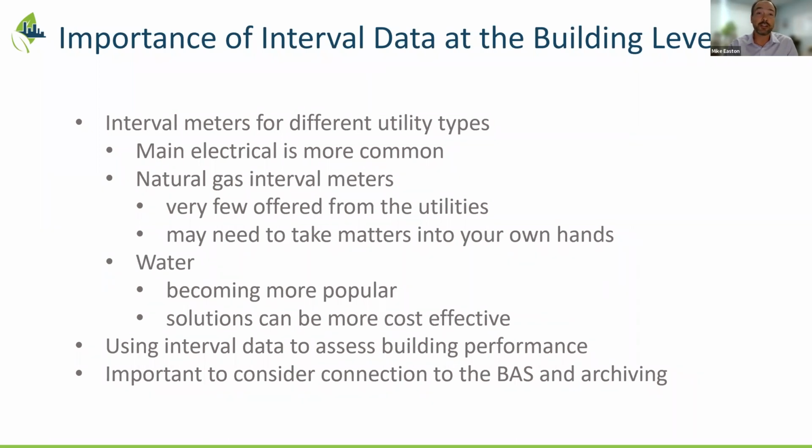If it's an energy management natural gas meter, then you have a lot more options open to you. This could include insertion meters, clamp-on meters, or redundant inline meters as well. When you're sizing these natural gas meters, you'll want to know the pressure of the load, the BTU load, and the pipe size so that a vendor can accurately quote you equipment and you get an accurate price on the installation as well.